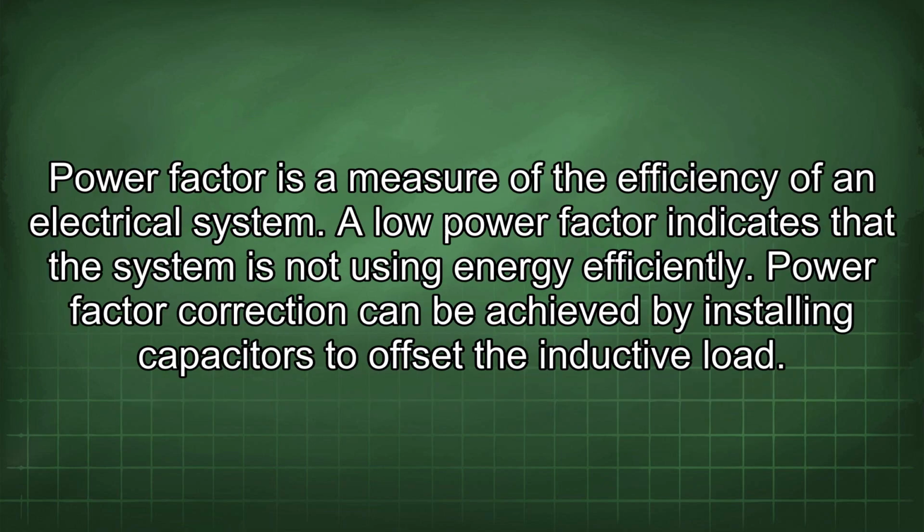Power factor is a measure of the efficiency of an electrical system. A low power factor indicates that the system is not using energy efficiently. Power factor correction can be achieved by installing capacitors to offset the inductive load.